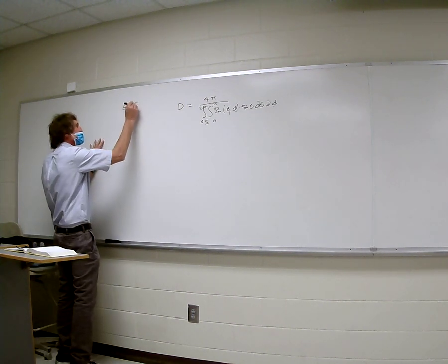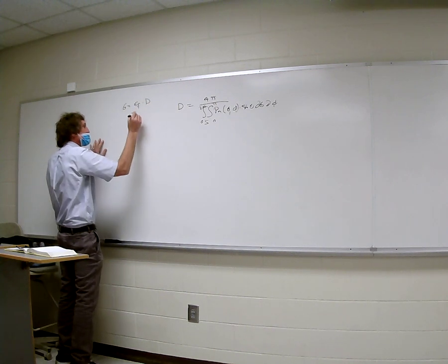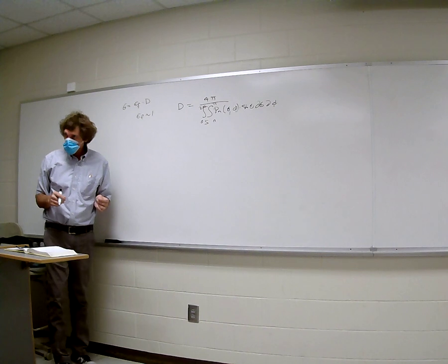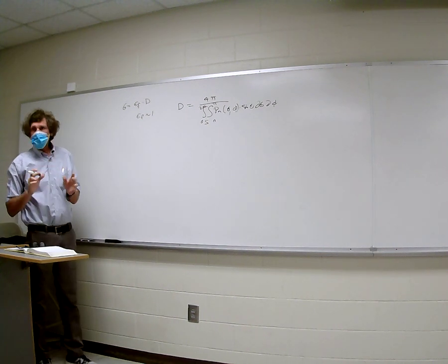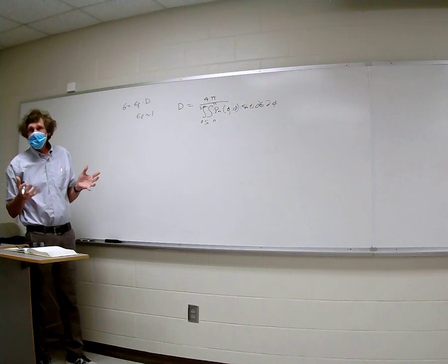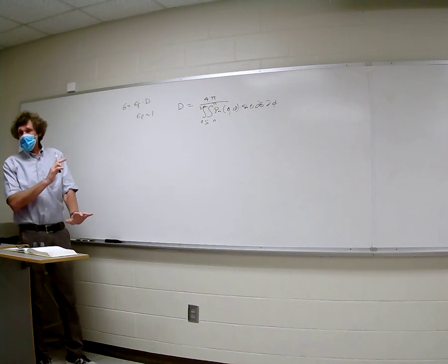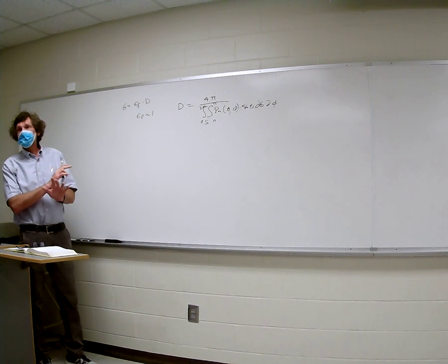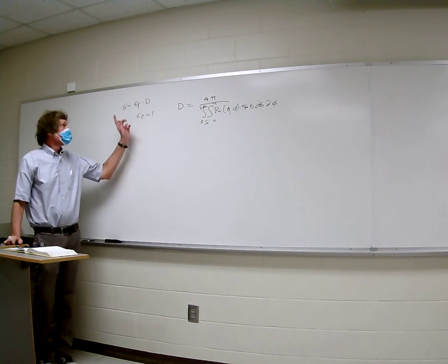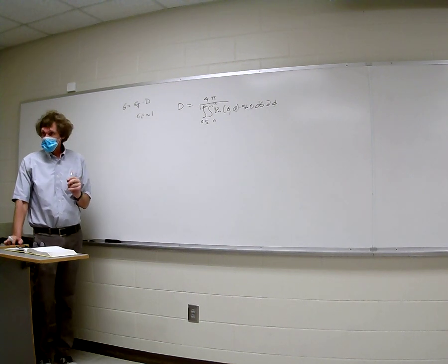Gain itself is the efficiency times directivity. Usually the efficiency is about 100% or 1. Okay? Almost, I mean, if it isn't, you got a problem. If it's like 30%, I mean, you basically got one of the worst antennas in the world. Now, if you're looking at how well something radiates that shouldn't radiate, then you'll need to calculate the efficiency. More on that later. With me?